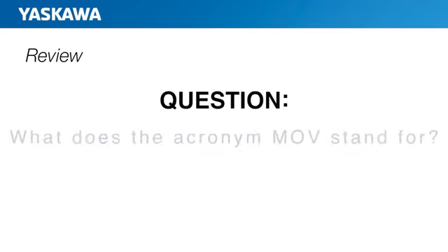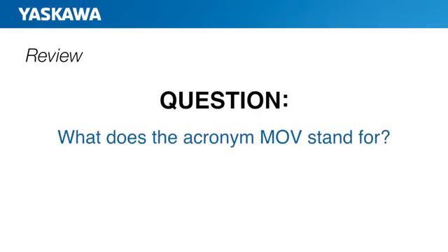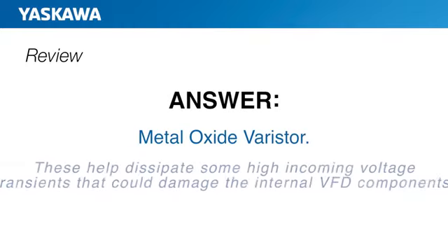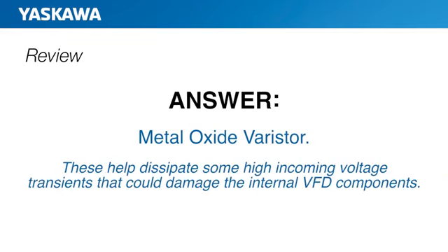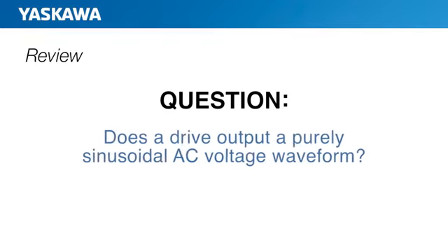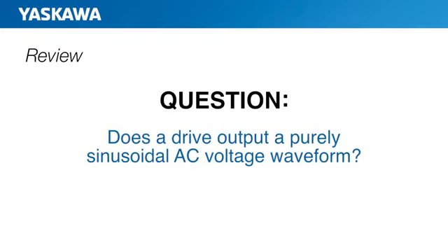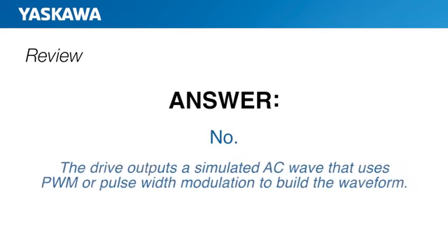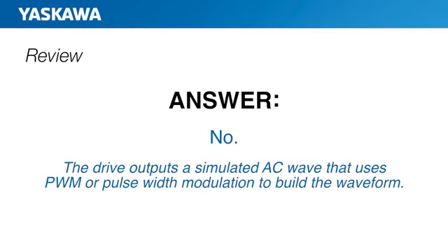Question number 2. What does the acronym MOV stand for? That's right, metal oxide varistor. These help dissipate some high incoming voltage transients that could damage the internal VFD components. Question number 3. Does a drive output a purely sinusoidal AC voltage waveform? No. The drive outputs a simulated AC wave that uses PWM, or pulse width modulation, to build the waveform.